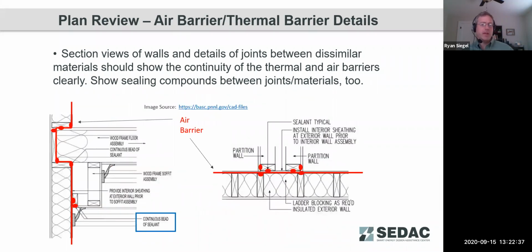So here's another one looking at some various walls, and here's even a soffit inside of a home, and here wanting to push that air barrier as far and not have it come into the space. It's not uncommon where we'll see, particularly in older homes, kitchen soffits where they didn't seal behind the soffit. And so that having that airspace go into the room is not ideal. You want to make sure your air barrier and insulation and thermal barrier are in intimate contact with one another.